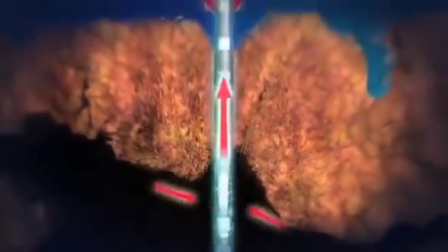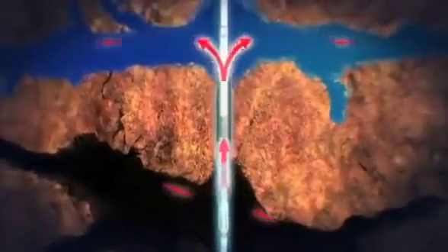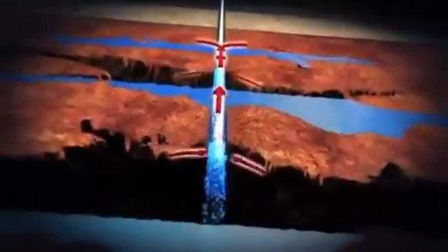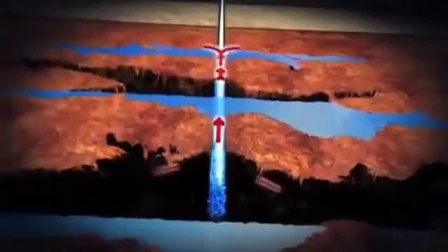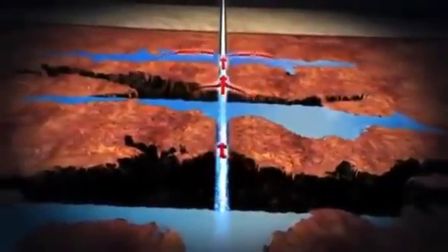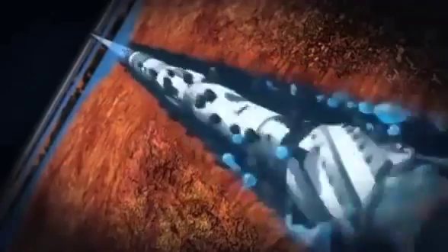Drilling continues, and a second lost circulation zone is soon encountered. Because the pressure is higher in this deeper section, the upper set of fractures continues to take the sacrificial drilling fluid and cuttings, and drilling continues without delay. In this manner, pressurized mudcap drilling solves one of the most difficult challenges faced by conventional drilling methods, and in doing so, makes previously undrillable wells drillable.